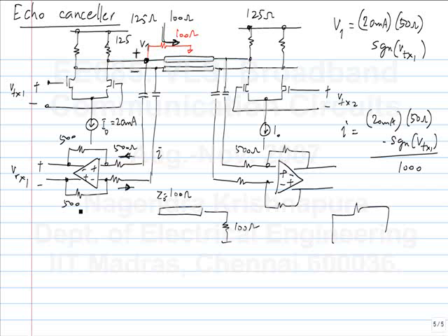And how would I cancel it? How do I cancel this? I want to make VRX1 equal to 0. But of course, the transmitter should be operating. So this is pushing in some current through this path, and I can use the virtual ground of the op amp to do current summation. That's what I do, and in that current summation, I'll provide exactly the opposite current.